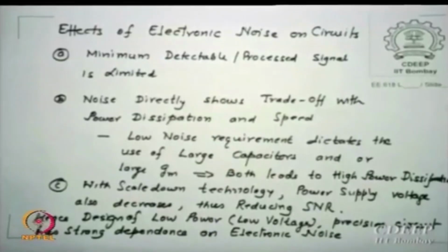Therefore noise issues are now more relevant in designs, as they were not so relevant in earlier technologies. Most of our analog designs are done only on 0.18, 0.25. Some students may be working on 0.13, and some smarter ones on 90 nanometers, but no one is working on 30 to 28 or 22 nanometer process because we do not have tools to do that. So this whole statement is humbug.